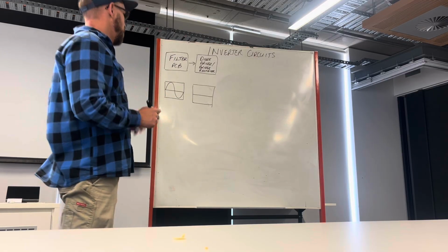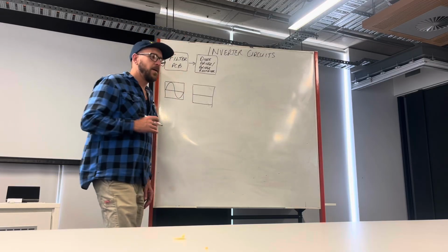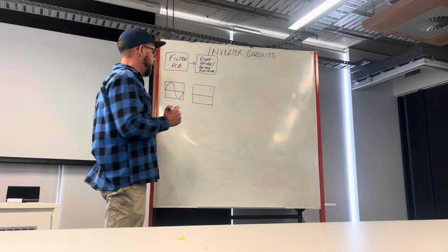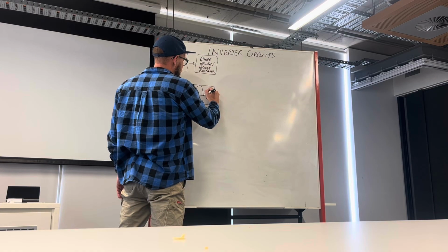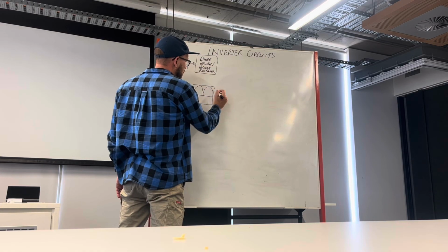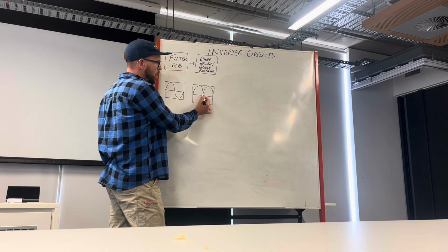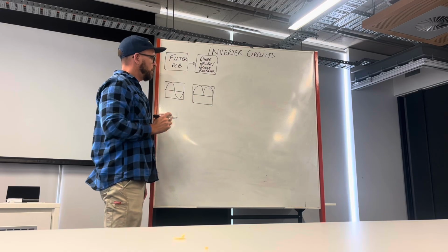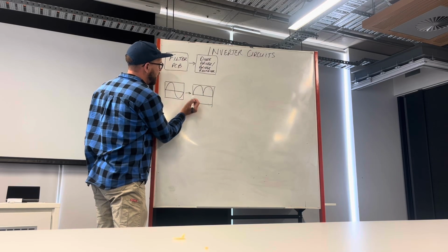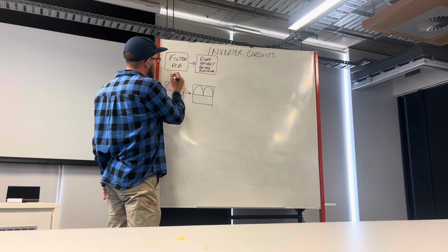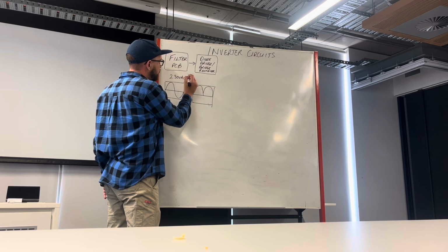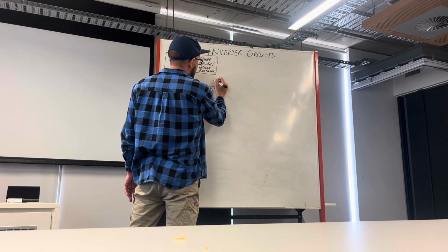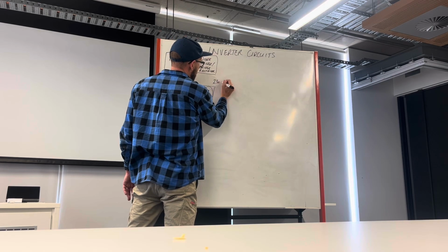Sometimes we measure a little bit higher, but what we do have is a fluctuating DC voltage we end up with. So if we draw it on the sine wave, current flowing in only one direction, but it's fluctuating. So at this point, if we're measuring 230 volt AC, by the time we're coming out of here, we might be 230 volt DC.